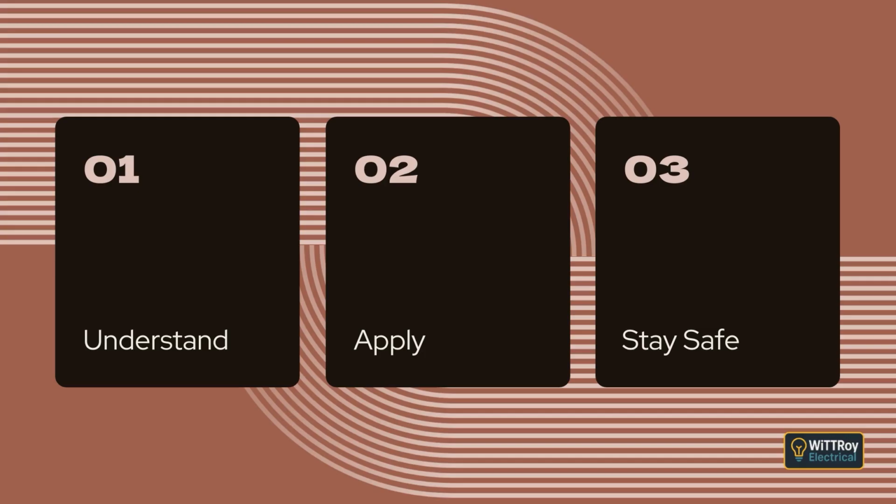Clause 2.2.4.4 Frequency. If the frequency of the supply affects how a device works, then the device must be rated for the system frequency, which in New Zealand is 50 Hz. Clause 2.2.4.5 Power. Equipment must handle the maximum power it will be expected to deliver without overheating or becoming unsafe.